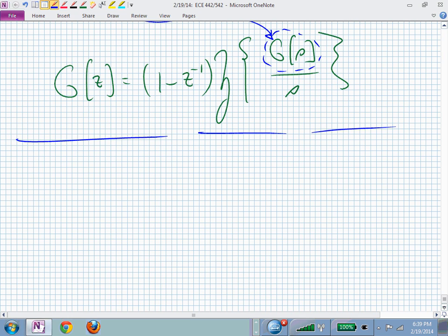But if you now are working and somebody gives you a 5th order system, you go, oh, let me find the state space representation, and I'll give him a state space zero order hold equivalent, and I'll keep the states there. Here we've buried the states, haven't we? Now I've just given you a G of z, a transfer function description of your zero-order hold equivalent.